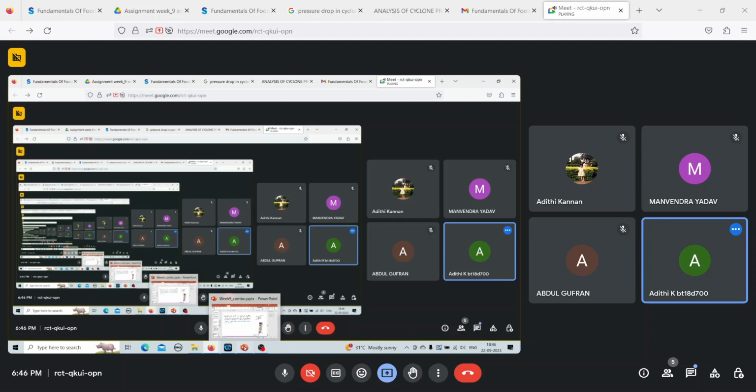So you have three types of filters. You have cake filters where you're passing it in a perpendicular direction, but in a cake filter your particles will be bigger than the filter size. So everything will get stuck on top. So that is the cake filter, where you'll have everything stuck on the top and you have the deposition of a cake. Whereas in case of a clarifying filter, that will again be in a perpendicular direction, but the particle size will be small so that it gets stuck inside the filter medium.